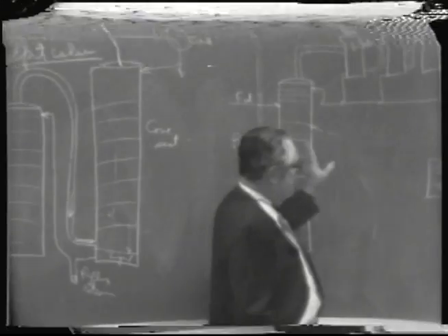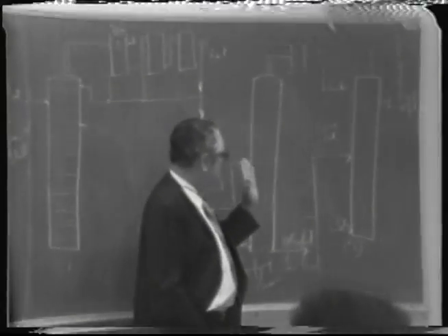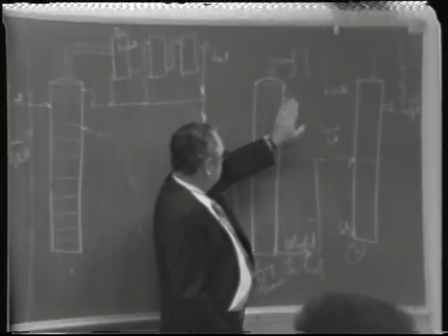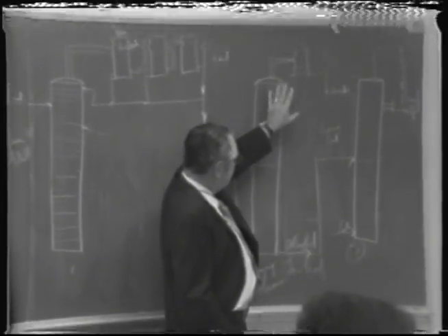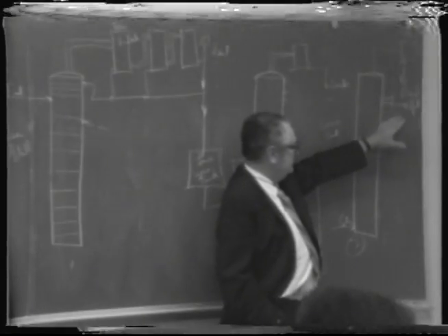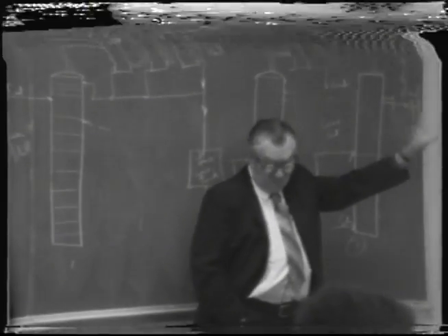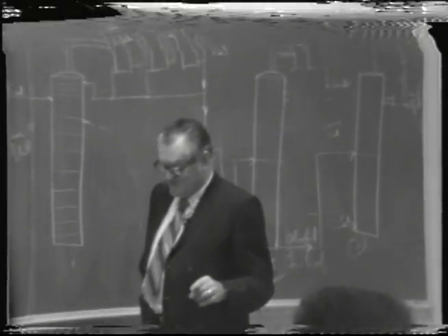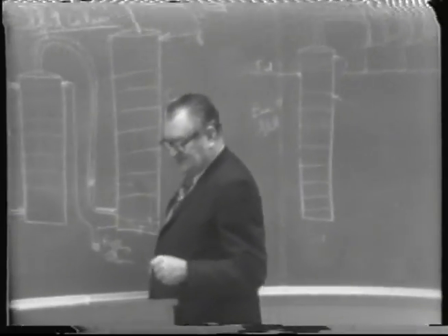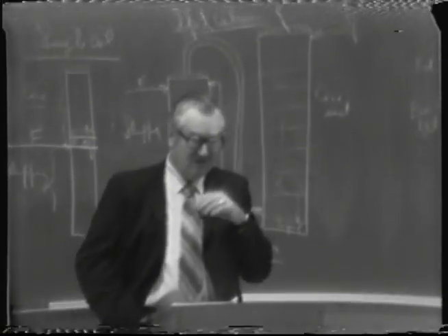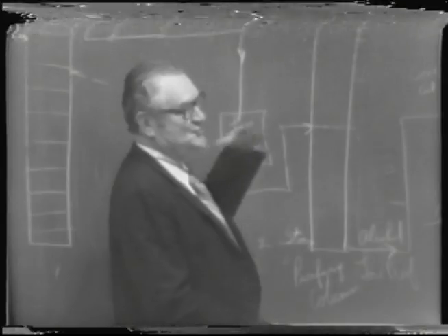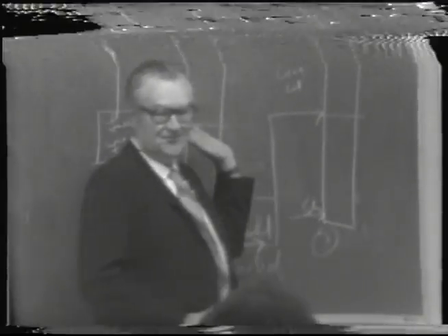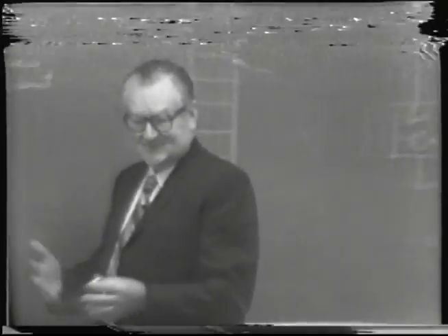But anyway, they'll have another 3rd column out here that they call an aldehyde column, in which they take the product that's been made without a complete head separation and run it through another column at full proof, at high proof, to remove the aldehydes. Well, it can be done. It works okay, but it's not quite as effective a separation as you'd get by running it through a low-proof column first. In other words, you can reverse the order, so to speak.